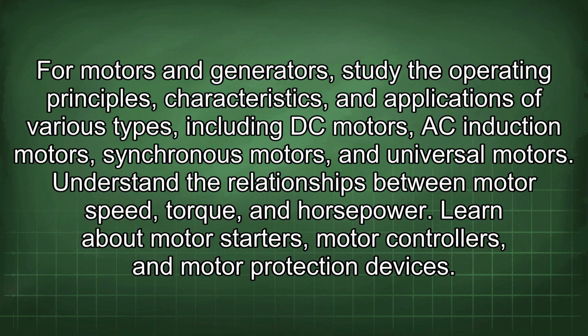For motors and generators, study the operating principles, characteristics, and applications of various types, including DC motors, AC induction motors, synchronous motors, and universal motors. Understand the relationships between motor speed, torque, and horsepower. Learn about motor starters, motor controllers, and motor protection devices.